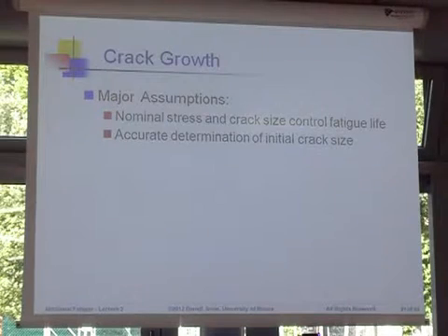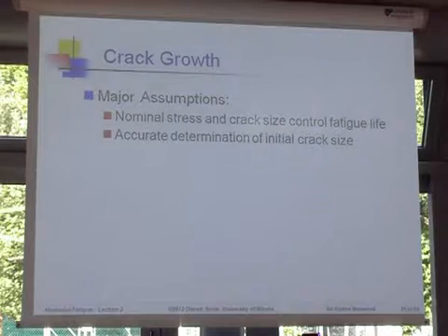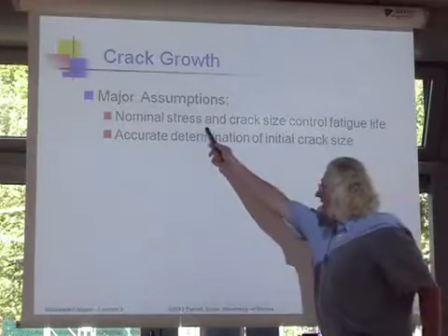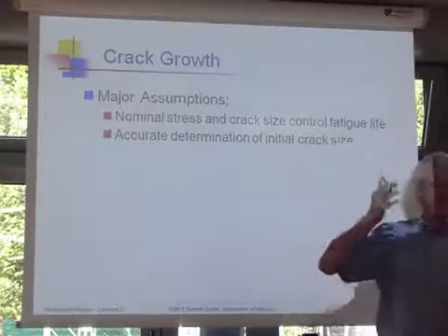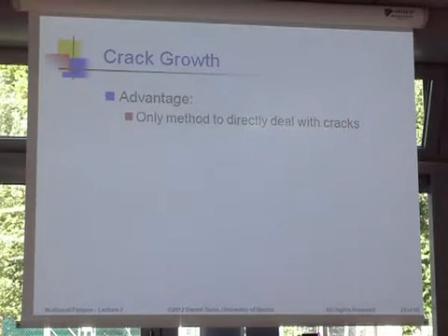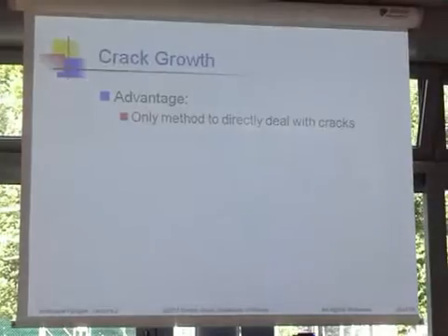All right. So now, the major assumptions are that the nominal stress and crack size control fatigue life. If you look at the practical implementation of this, getting the nominal stresses is relatively easy, and we don't really know so much about what the crack sizes are in structures. I guess this really is the only way of dealing with cracks. As far as I know, no one has a better way.